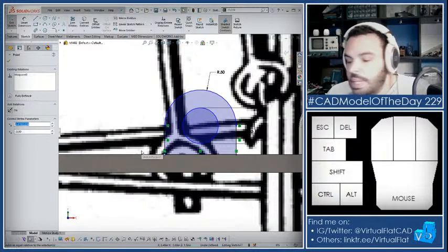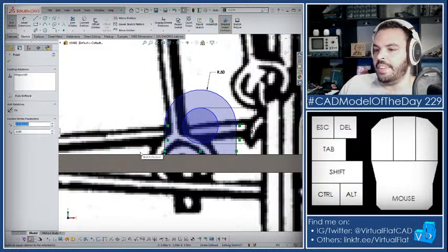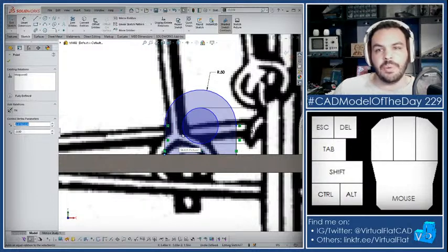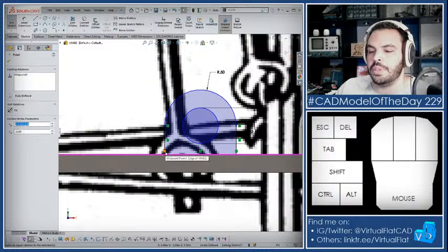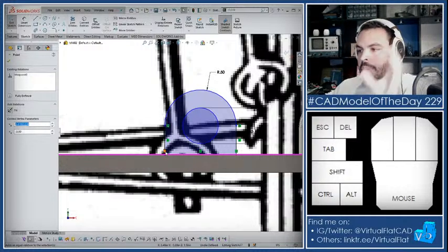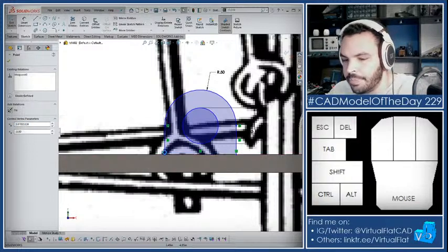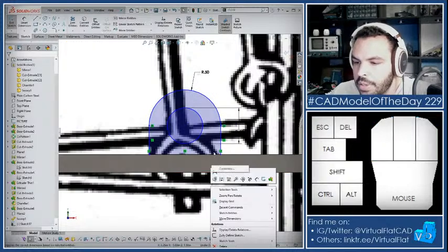All right, so I'm trying to move this to the left, and this took me a while to get the sense for. I have like a hawkeye now: if a sketch is not letting me do what I want, I just know what it is. See if you can figure out what's going on. Pause the video if you feel like, but basically I accidentally snapped a midpoint. So instead of saying coincident, this says midpoint, which is more specific than coincident. So this is what's keeping my sketch from moving to the side. So I'll delete that, and yep, now my sketch is free again.